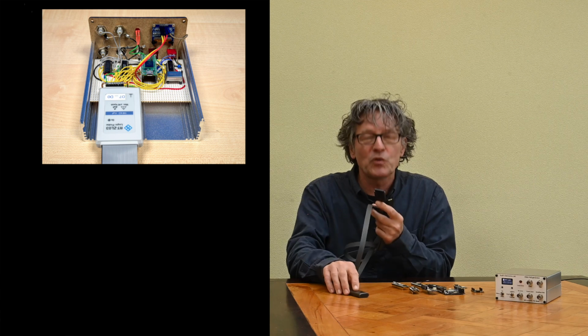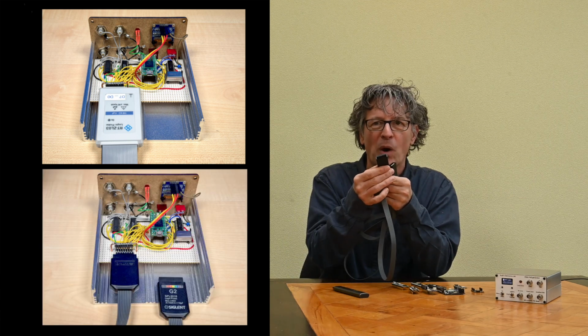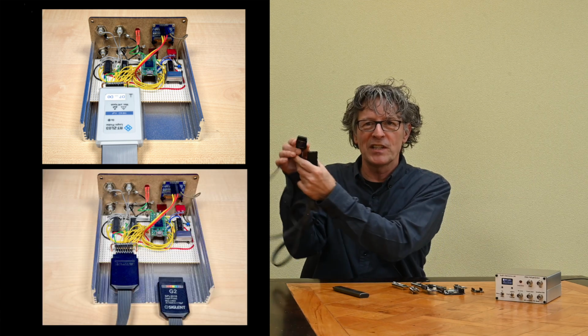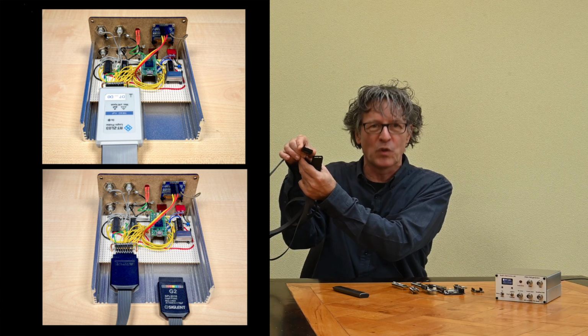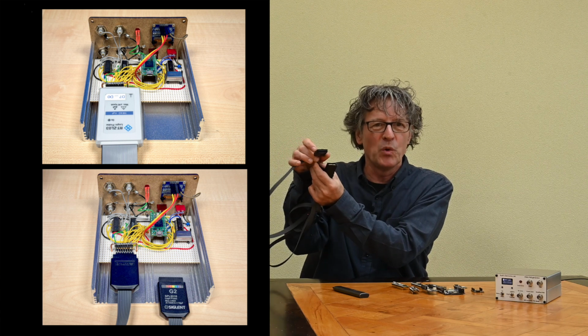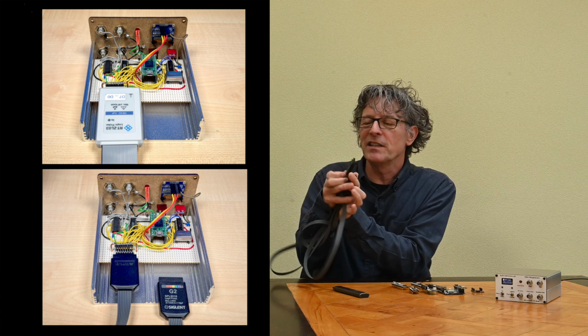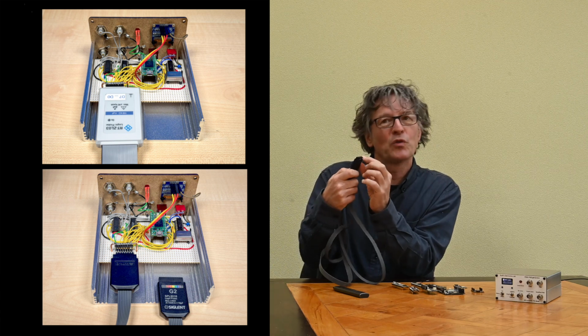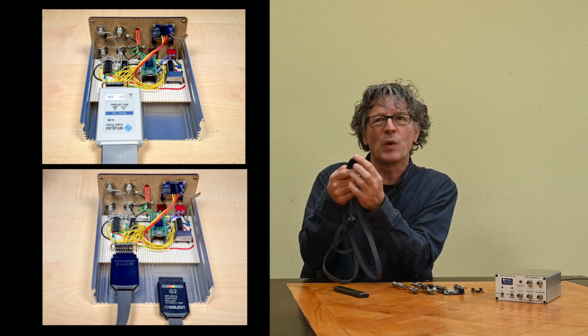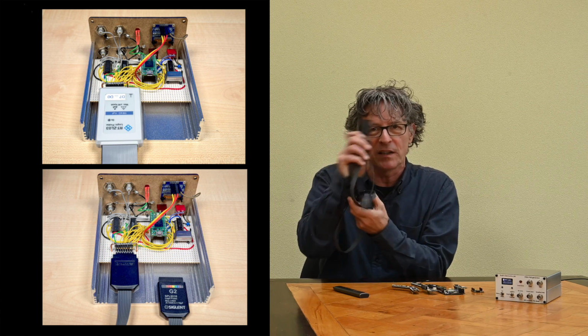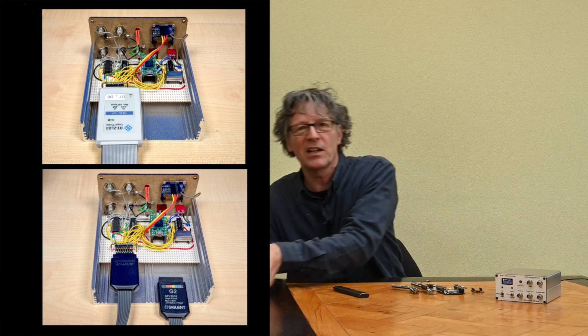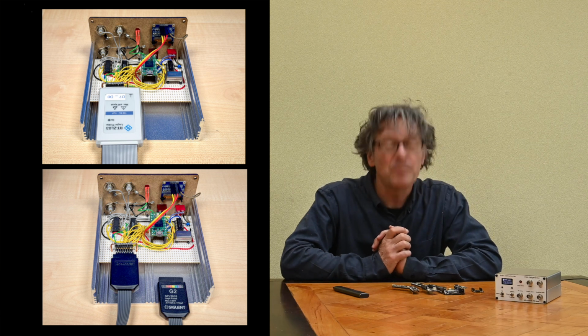Actually, it was not too hard to make them compatible with both. The only thing is that you have to put the Siglent interface kind of upside down, because it has the pins and the ground row in the opposite way. But it works perfectly. The Siglent interface has 2 rows of 10 pins, but the outer pins are ground and are not used in my design, so it just stays compatible. There's just a space that you can plug it in. But this we basically got here for debugging purposes.